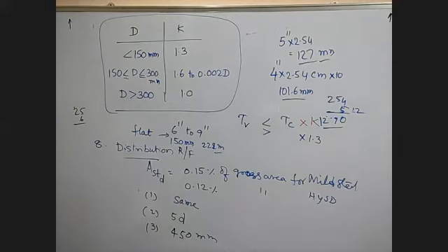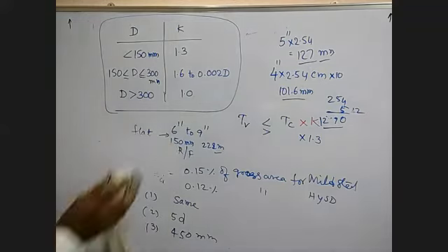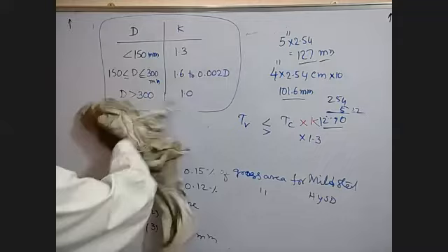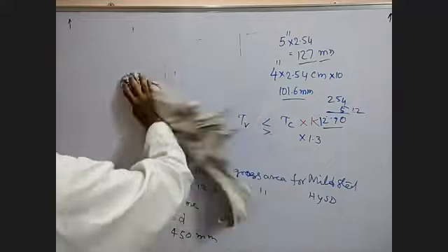And one more important thing here: in the slab, 50% of the bars should be bent up at the support. Mainly to take care of the shear and to resist the negative moment developed at the support. So how do they draw this diagram? Since you still have 10 minutes left, I'll explain why 50% of the bars should be bent up at the support.